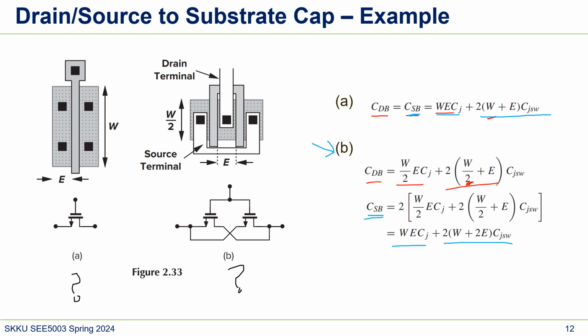Does it make sense? Can we say it's worse, it's bad? Probably, but sometimes it's okay. Because when we see the circuit, NMOS, and source, usually the source is connected to where? Ground. And where does bulk go? Bulk goes to ground too. So in this case, V source bulk is 0.